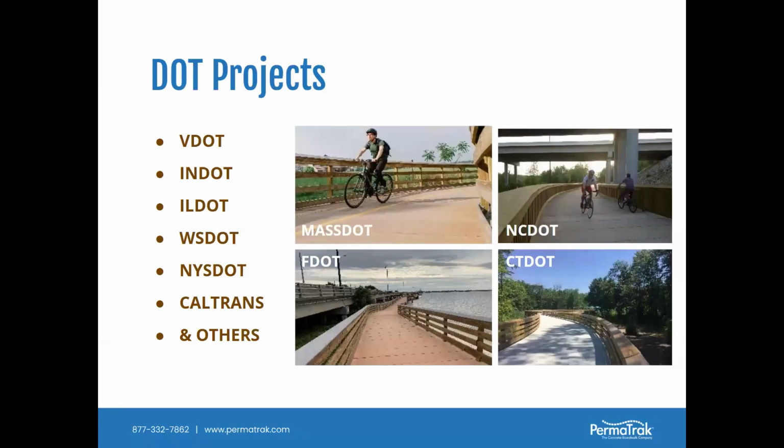For DOTs, certainly you can use any kind of boardwalk system on public projects. However, you're not going to find a boardwalk specification. So a lot of times what you'll have to do is utilize a special provision or a supplemental specification and then just reference back to the DOT material standards.